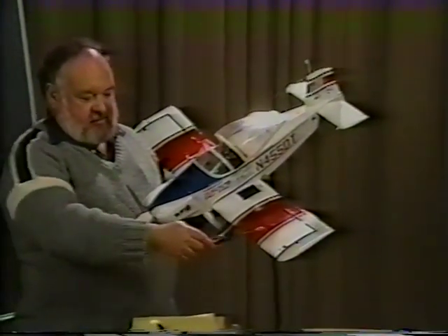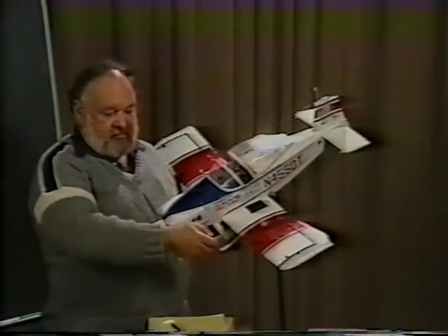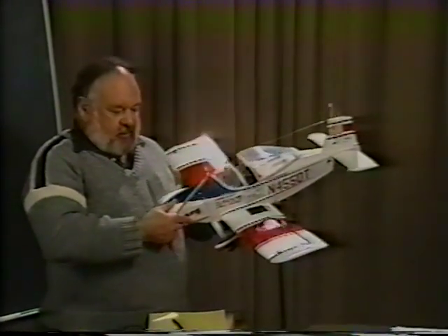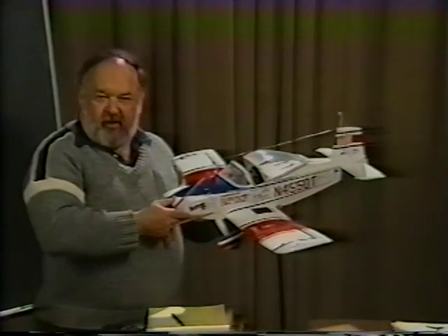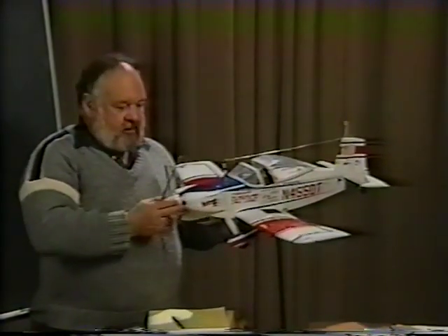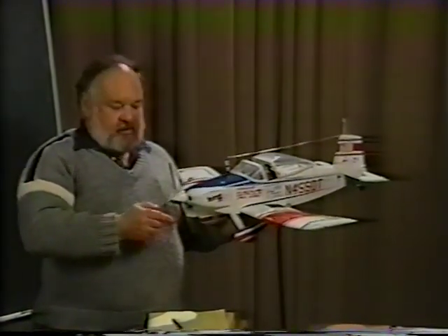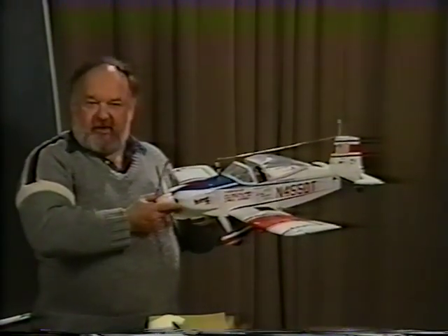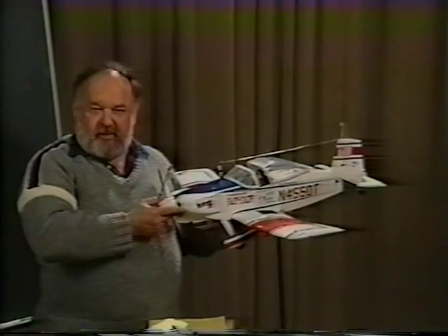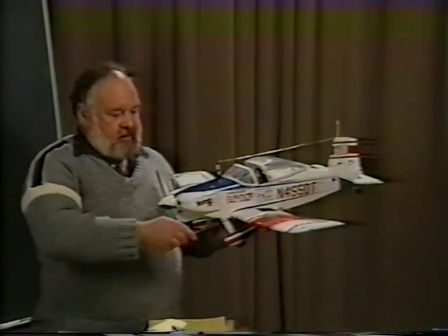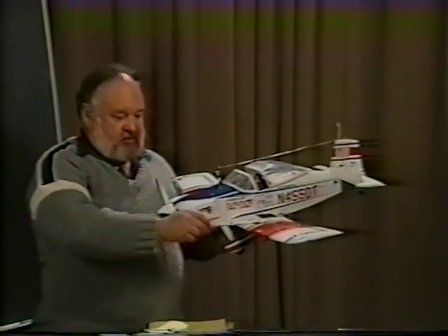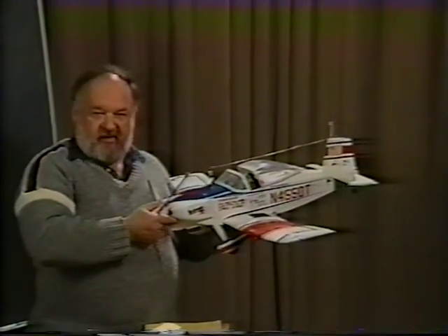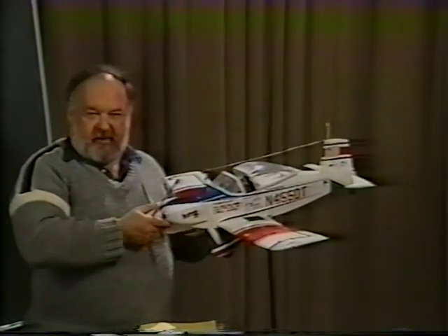John Thorpe has a constant chord wing. The Reynolds number at the tip is the same as at the inboard section, so that's quite good. But he does have this break in here, which from a stall pattern standpoint isn't ideal, but from a structure standpoint was quite good. What he has here is an inboard section of the wing that he could make as a one-piece spar going all the way through the wing. And the first set of joints on a spar isn't until you get to the break in the wing itself, and that's where the spar can go thinner and lighter.